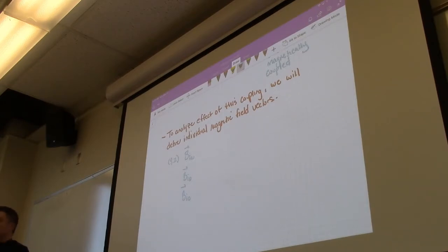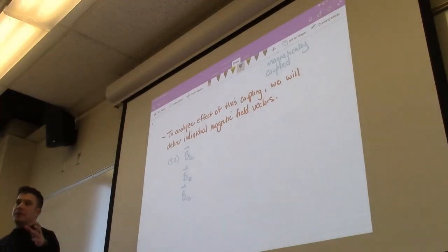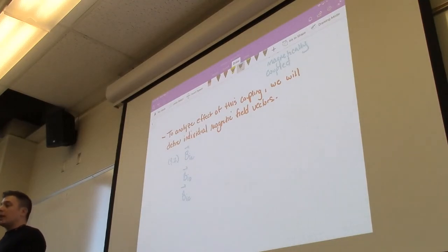These are the magnetic fields that are associated with the armature windings. So the armature reaction describes how phase A reacts to the currents flowing on phase B and phase C. Each armature winding, stator winding reacts not only to the field winding, but also to the magnetic fields generated by the other windings.